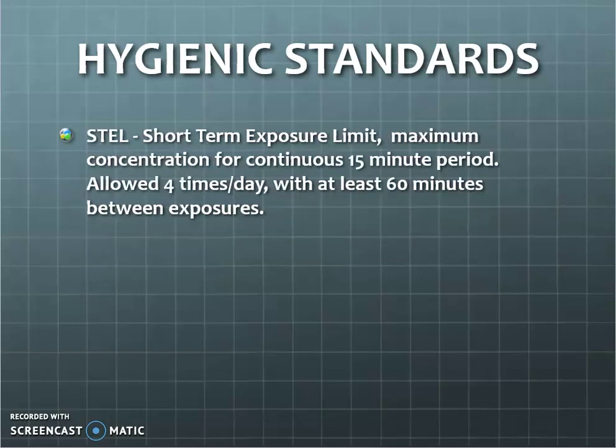Then we have STEL, short-term exposure limits. That's the maximum concentration for a continuous 15-minute period. This is allowed for up to 4 times per day with at least 60 minutes between exposures.